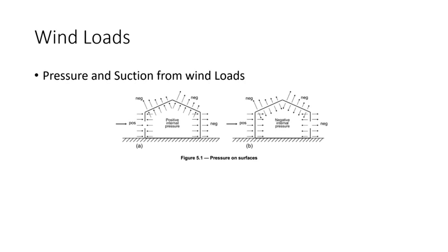There is a certain value of allowable drift for any structure. If it is crossing that, then again you have to design your structure. Especially for wind loads, steel structures will have a huge impact, unless they are not high rise. If high rise structures are there, then you even have to do analysis for wind loads for concrete structures also. And there is one test, the wind tunnel test, which you have to do, unlike the empirical way of applying wind loads to the structure.